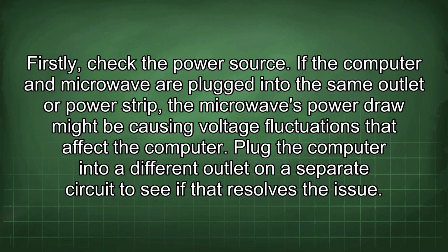Firstly, check the power source. If the computer and microwave are plugged into the same outlet or power strip, the microwave's power draw might be causing voltage fluctuations that affect the computer. Plug the computer into a different outlet on a separate circuit to see if that resolves the issue.